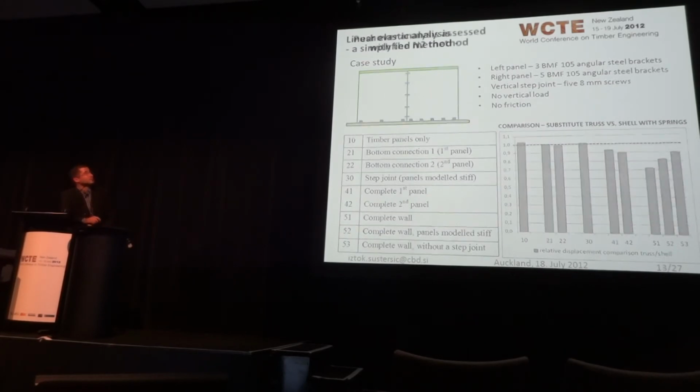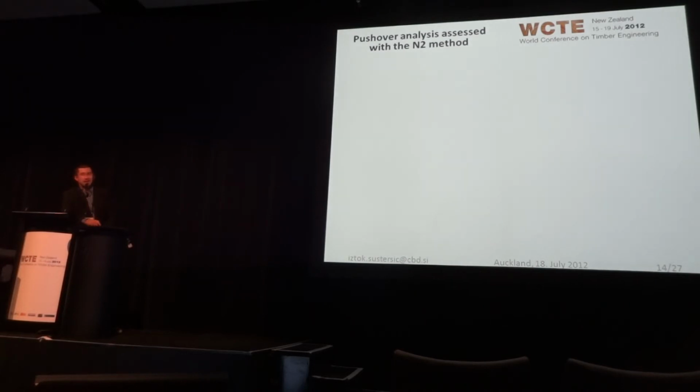Okay, I have to move to the pushover analysis. I've decided to put a slide in because some of you may not be well acquainted with displacement-based design, but it's actually very simple. So this is the pseudo-acceleration spectra, which pretty much everybody who has dealt with seismic analysis knows. This is the pseudo-displacement spectra, not that common in engineering practice, but if we put those two together, we have the so-called AD format spectra, the acceleration-displacement spectra.